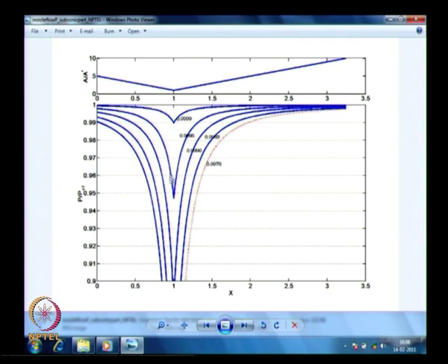It is dropping more seriously, and if I make it 0.9990, it is going even below 0.9. Okay, I have not shown it very clearly here. And if I keep on doing this, I decrease it by a small amount, there is a point where it becomes choked at the throat. That particular calculation happens at 0.9976. This happens to be your first critical pressure.